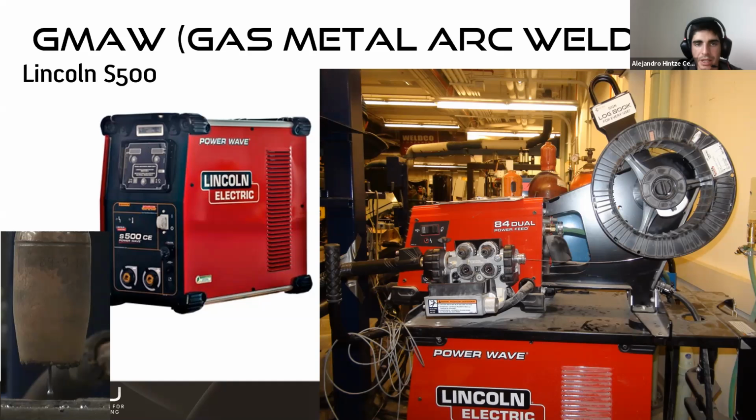a pretty sophisticated power source in which there are a lot of uploaded preset programs that you can choose from. If you're welding a certain type of material with a certain gas, you can choose the program, and then the program will have already loaded all the parameters that you need. But you can also change them and customize the program.